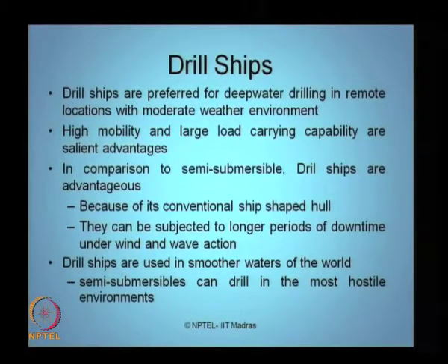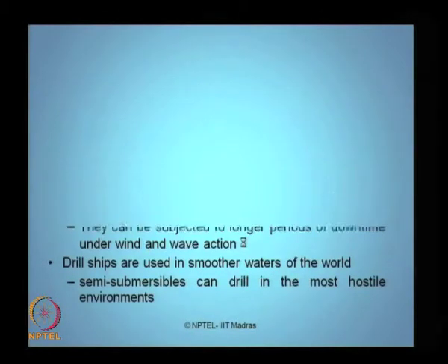Therefore, drill ships cannot be used in rough sea states. So, it is recommended that drill ships be used in moderate sea states. Semi-submersibles however can drill in most hostile environments as well. So, there are some merits of drill ships in comparison to semi-submersibles, and there are some advantages of semi-submersibles in comparison to drill ships in terms of working weather environment.